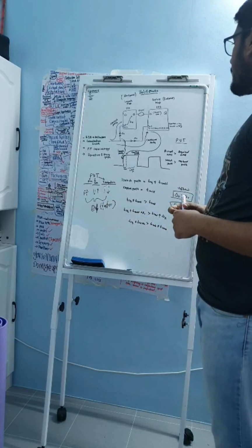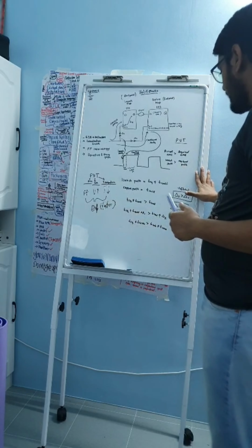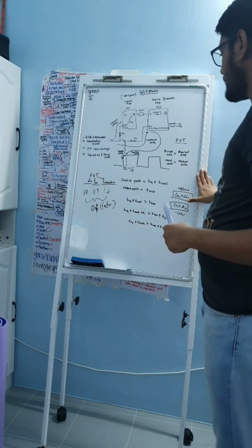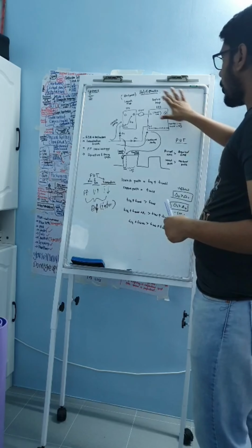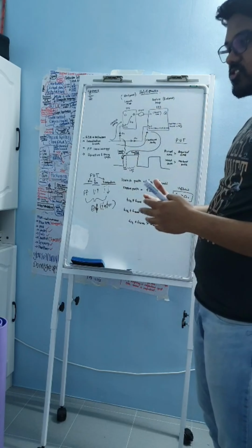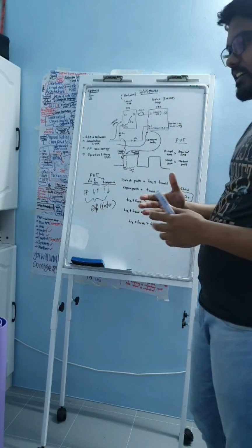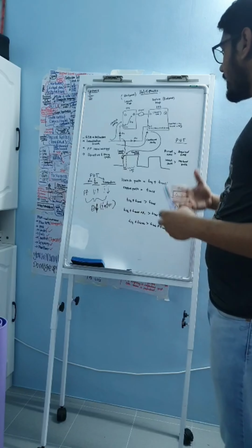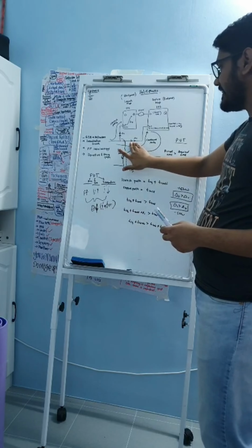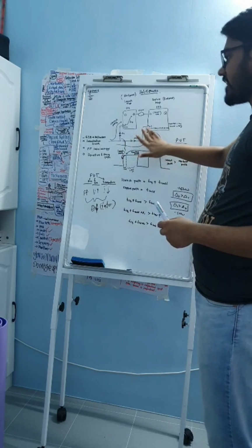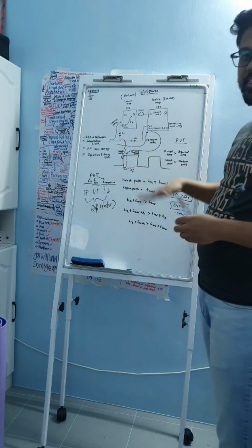So I hope I've covered most of it, and that you understand the check. For hold, it checks on the same clock edge. For setup, you are checking on the subsequent clock edge, as I mentioned earlier. And what happens if a delay has been introduced in the clock path? If it is more, then it's going to violate. If it is less, then it's pretty good.